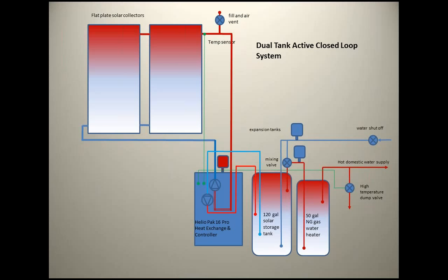That's true. And there's a couple of things that make solar hot water systems really work efficiently. One is you've got a family. You've got a lot of hot water usage. If you only have a couple of people, it's not as good as if you have a family. The second thing is if you're willing to adapt some, so you do a lot of hot water use in the morning, then you're getting this water that was hot the night before going through this system.